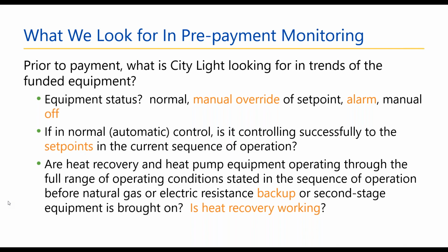And what we're looking for at that point is whether or not the equipment is operating. Is it actually off in alarm? Is it on? Is it in automatic normal control? Or is there some kind of manual override of the set point? Or is it in manual off? And I find not infrequently there is one of these non-standard states happening when I first walk on site.